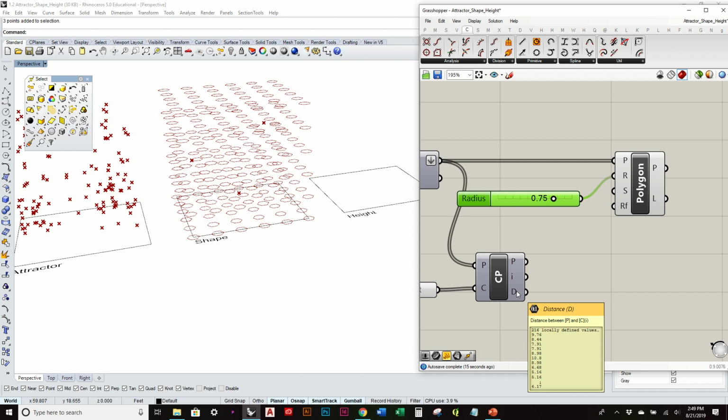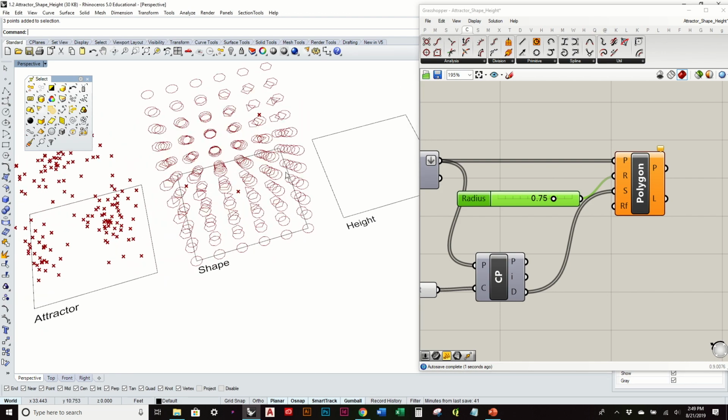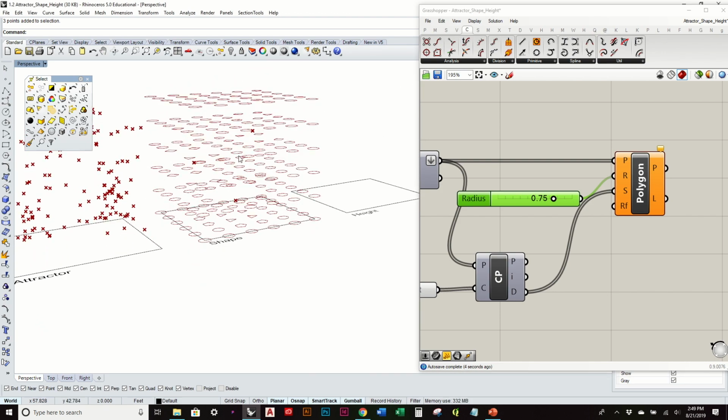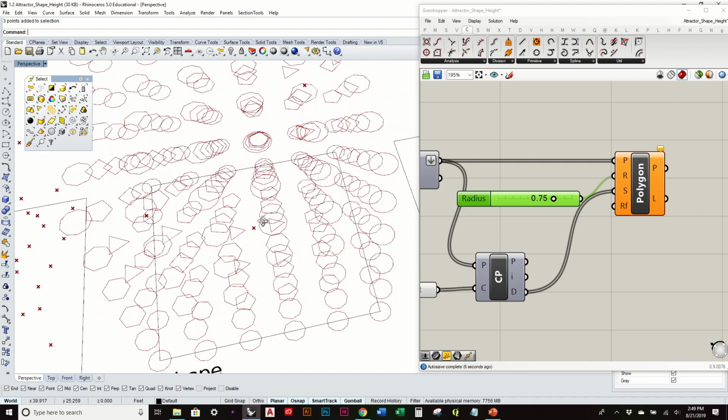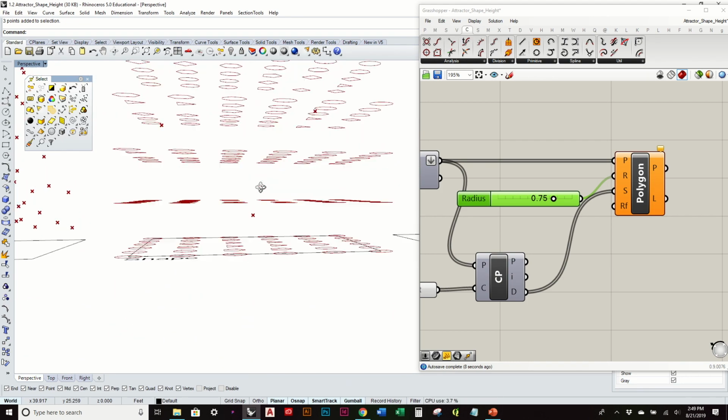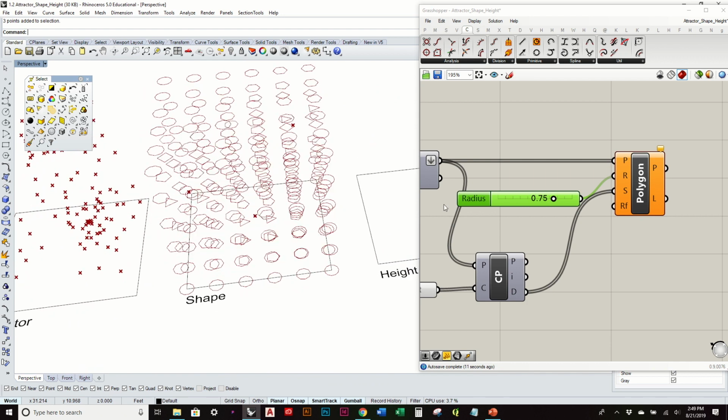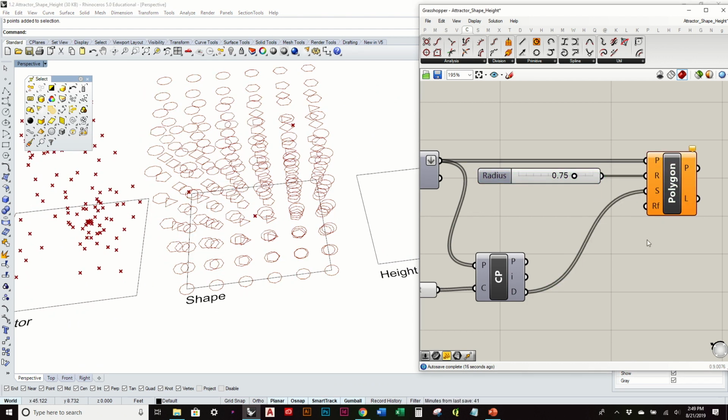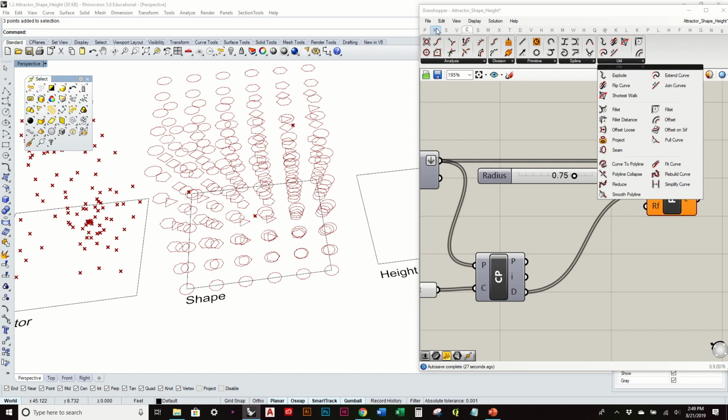What's going to be an issue is if it's less than 3, or less than 2 even, that segment's not going to actually be a geometry. And that's why we start to get this orange color, because that can't be a shape if it's got less than 3 segments. So similar to what we did before, we can actually create a cap to that. So anything that's less than 3 is actually going to represent 3.